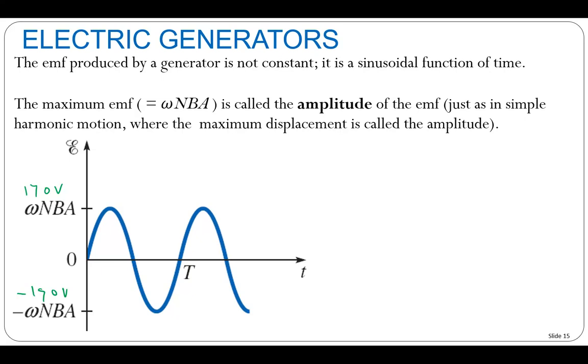What is the average voltage here? That's the blue line. What's the average? 0. So V average is 0. Well, that makes things a little annoying. For AC voltage, your average is 0, so we don't go ahead and talk about our AC voltage as being 0 volts, because it doesn't matter what the peak voltage is, you always get the same value.